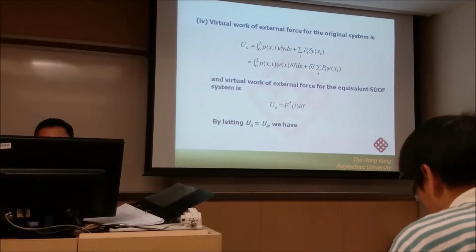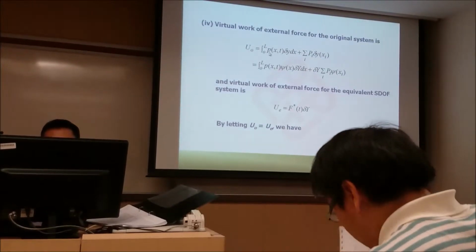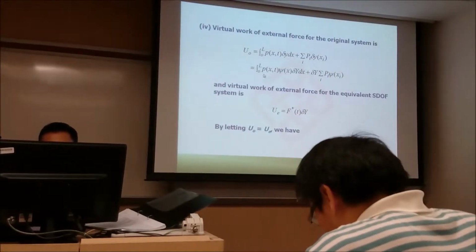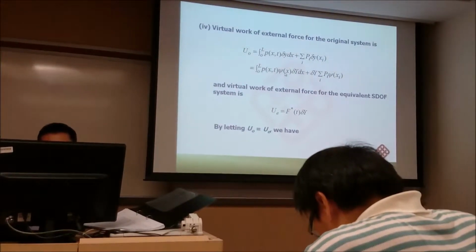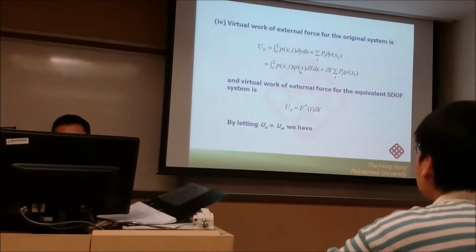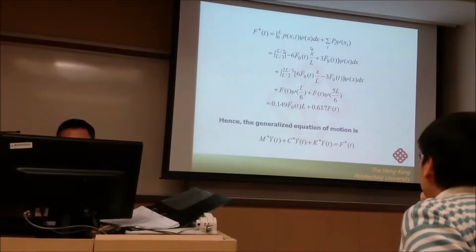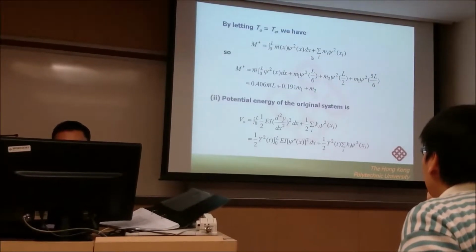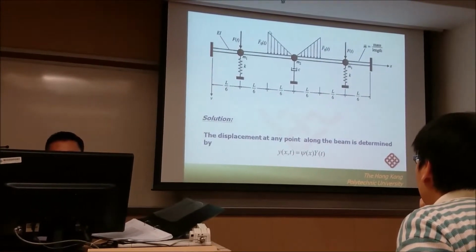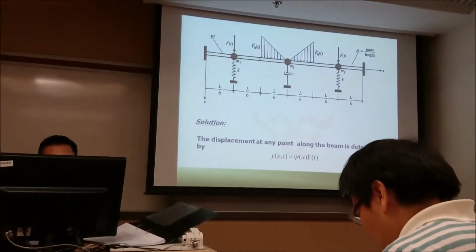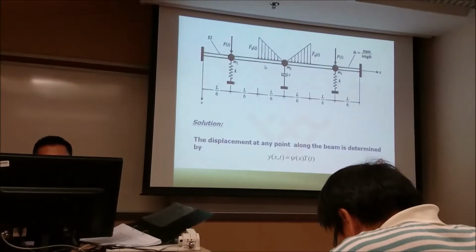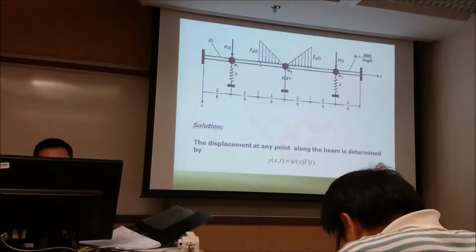And how about the force? For this problem, we have both distributed force and concentrated force, so you have to consider two terms. For the distributed force, you have to complete the integration. I want to mention this because some students make mistakes in the calculation of the integration. The distributed force is applied just for one specific range, not covering the whole length of the beam. So the integration should be taken from here to here.